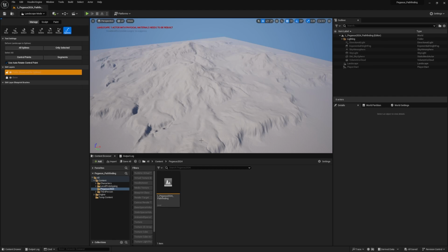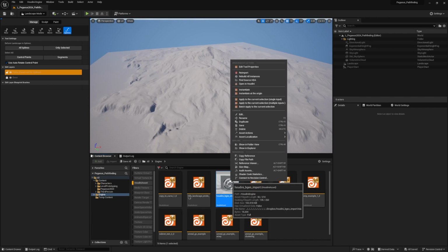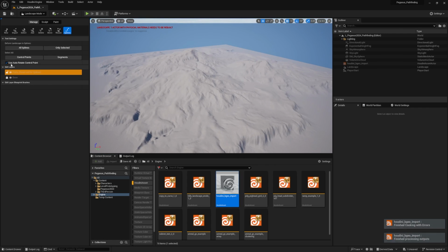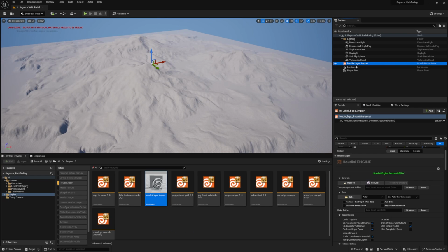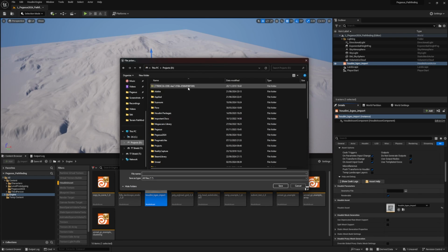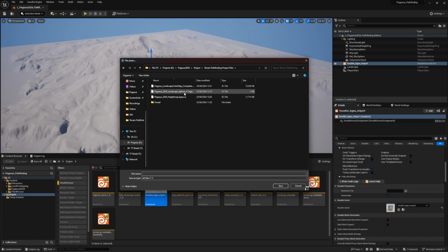Back to Unreal. And just like we did before, let's go down to the engine directory, turn on the Houdini asset filter. We're going to instantiate a BGO import at the origin. We're going to leave the spline editing mode. And then we're going to click on the Houdini BGO import. And we're going to go down and select the splines that we just exported. There we go.